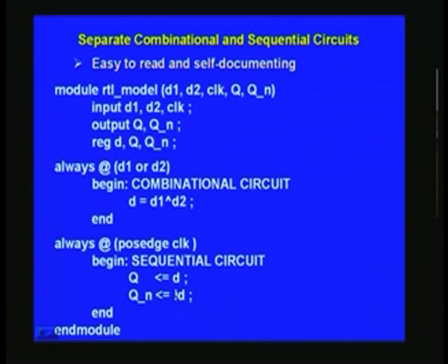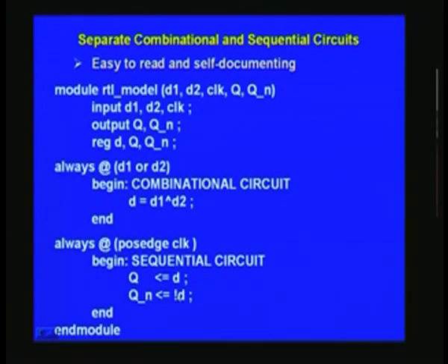So here we are inverting this D, although we are inverting, actually you will be surprised in the synthesis tool to find two flip flops there, not just one flip flop. So our intention was just to make one flip flop, and the other one is merely an inversion of this, but unfortunately the tool does not have that much intelligence. And if you want, you will have to circumvent it.